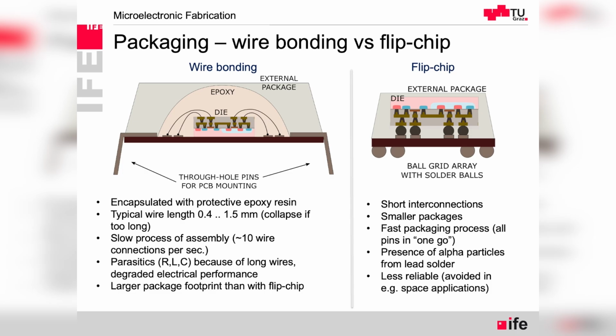So what we have are these attachment balls, and there has to be alignment between the package and these deposited balls or metal pads. And then in the thermal process, it's integrated together into a solid structure.